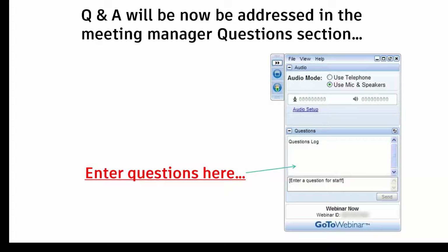Any others? As far as a guideline for your starting mesh size, there's a couple of obvious caveats to that you typically want to try to encompass. For starters, we want to make sure that your element size is at least equal to your thinnest section of the component. We want to make sure that we're not creating a really large deviation in the mesh element sizes.